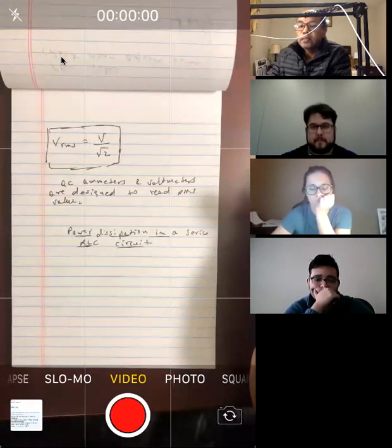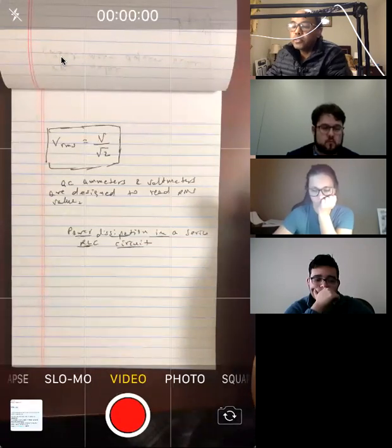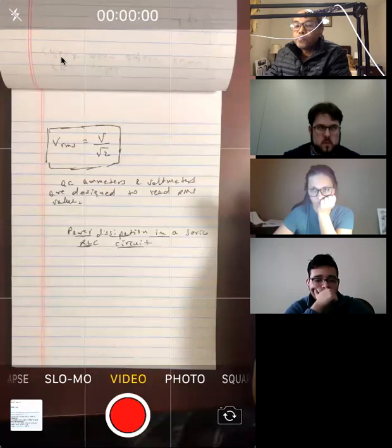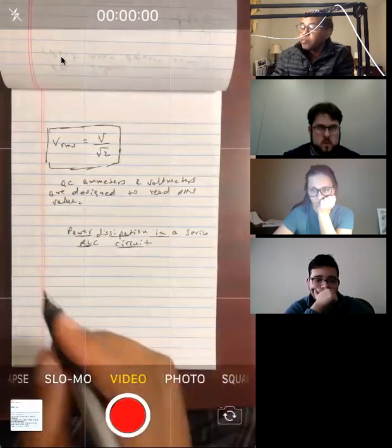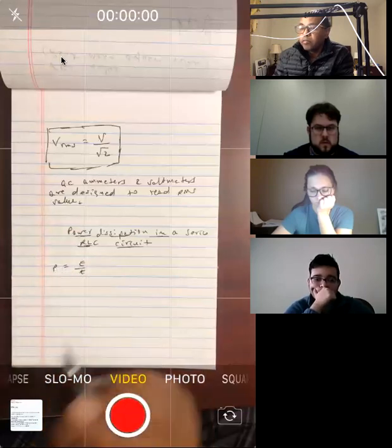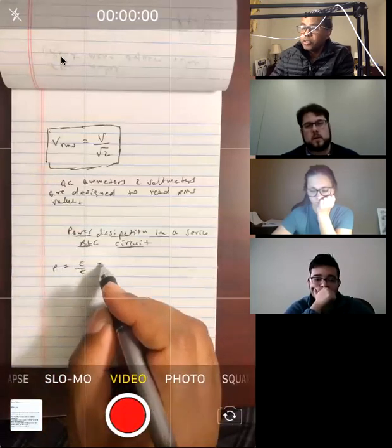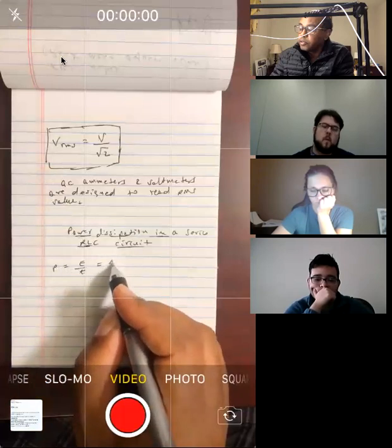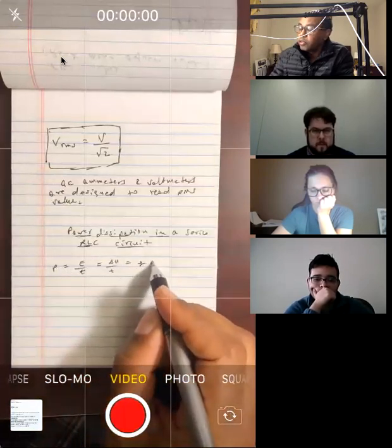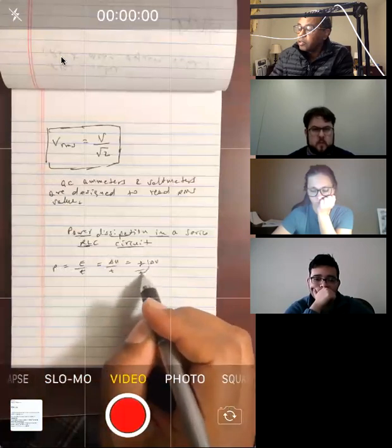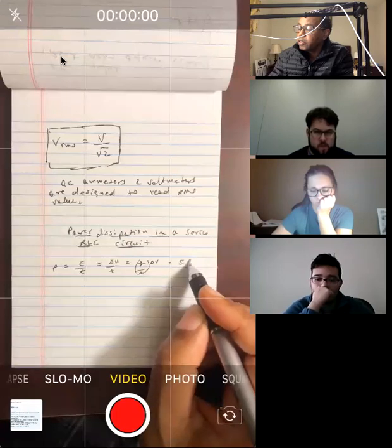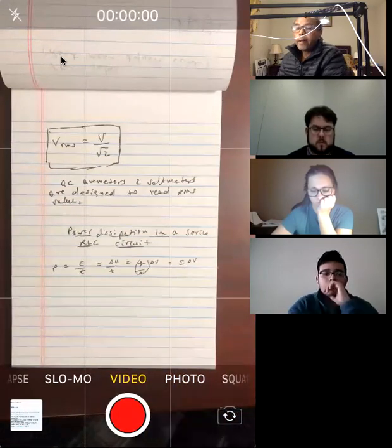How do you calculate power in terms of voltage and current? Power is voltage times current, right? Power is energy divided by time. Energy, or delta U, in this case for electricity, divided by time. But this is charge times delta V, and we divide by time, and charge over time is current. So you get current times delta V is power, okay?